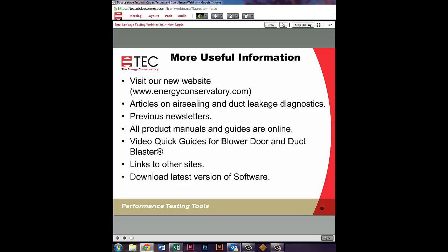Let's see, what else do we have? How would one know if they have enough system return air if all the ducts are sealed? So after the technician is done sealing the ducts with mastics, he would turn on the air handler and measure the external static pressure. This goes back to a traditional HVAC technician test. When all of that extra ductwork gets sealed, the external static pressure is going to start to climb. And when the external static pressure climbs, that means there's a reduction in airflow.